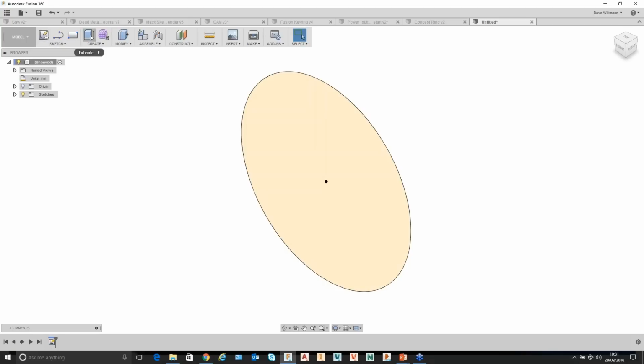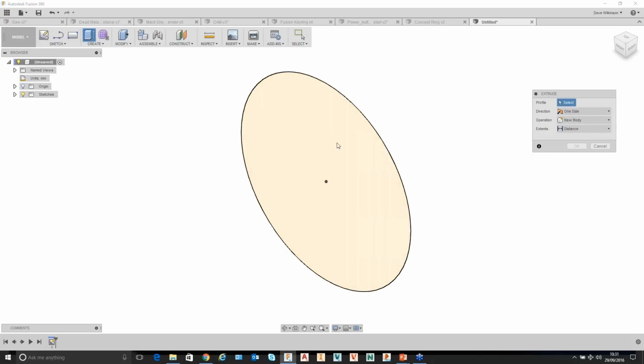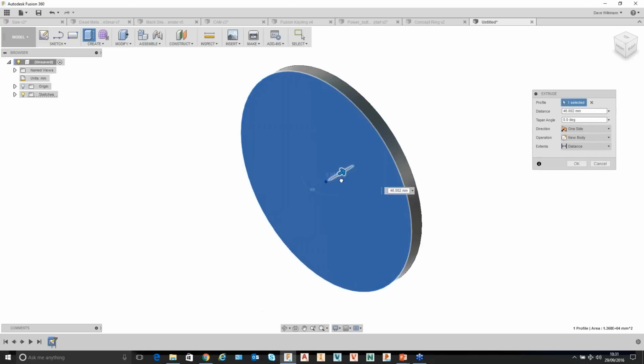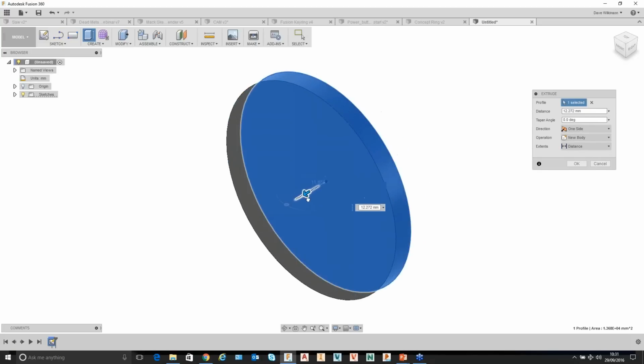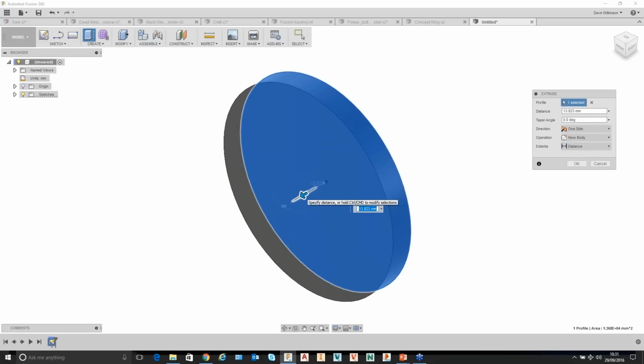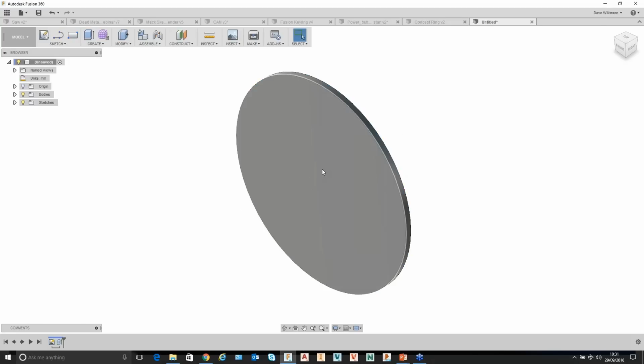And if I move along a little bit to my next icon, I can see I've got an extrude command. What this enables me to do is extrude that disc as a solid. Now what's particularly useful here is I can do it as a freeform sort of size, and if I'm concepting, drag some ideas down very quickly and easily. Or in this case, I want to be specific and say 4 millimeters. I'm going to drop that down.